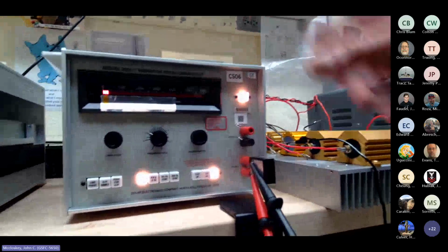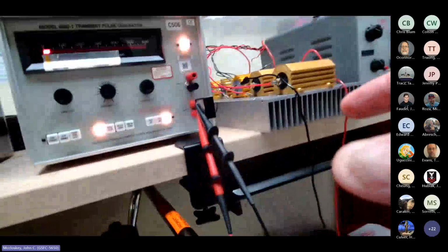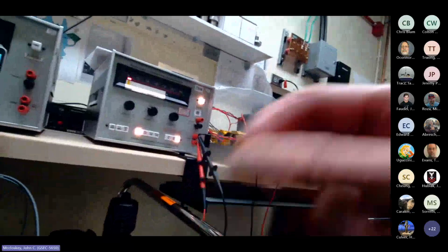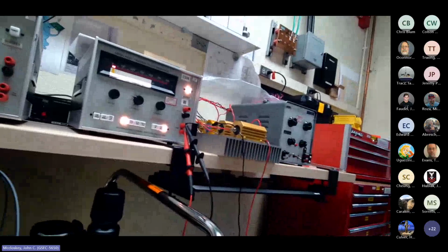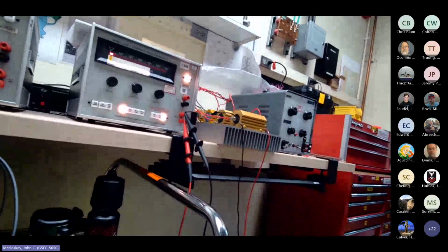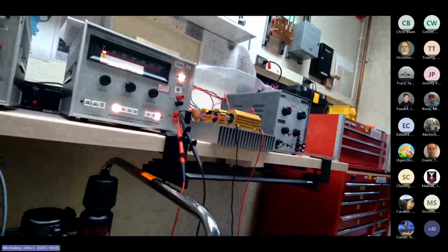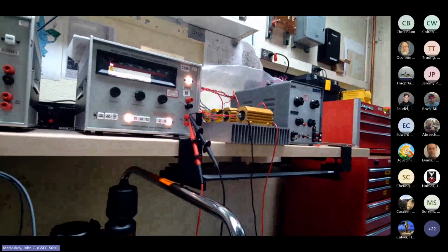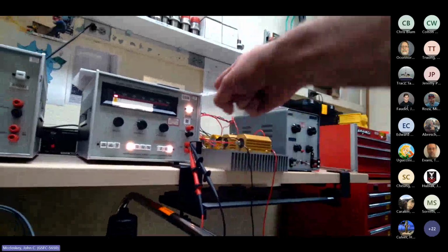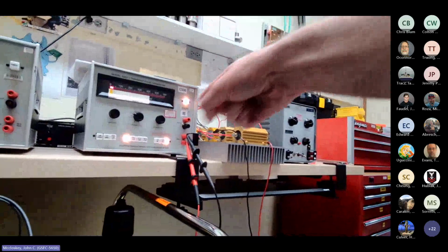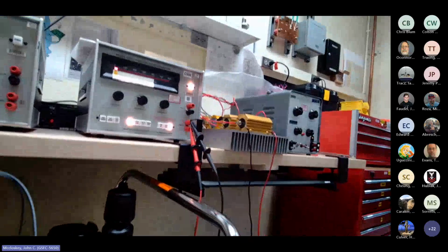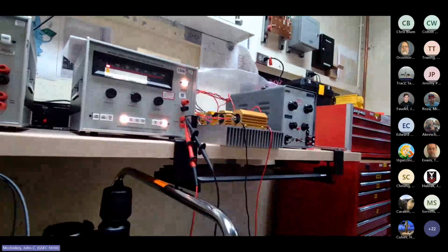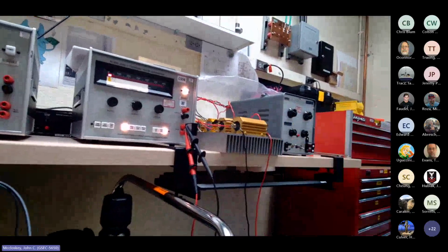Because remember, if you've got a transformer that's hooked up in series with your power feed, until you've actually energized the drive circuit, you've just got the inductance of the secondary of the transformer, which could be millihenries, in series with your power feed. And that's inviting instability and ringing and possible damage when you turn the equipment on. So don't do that. If you're doing the series injection method, you want to turn on the generator with the amplitude all the way down, turn on the EUT, and then when you're ready to test, you turn up the amplitude, and you should be monitoring what you're putting into the EUT.